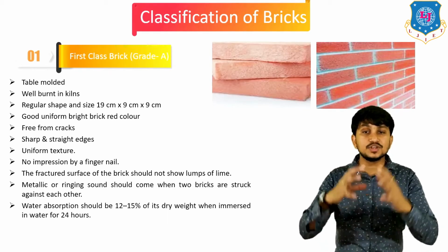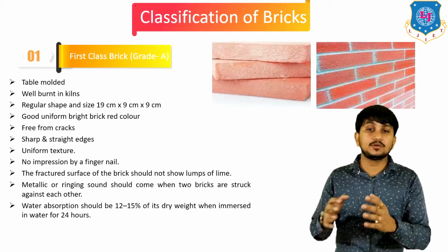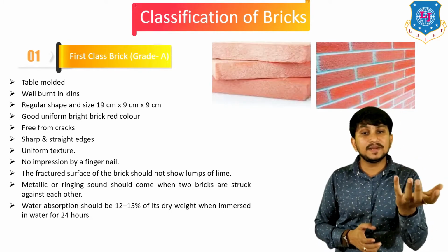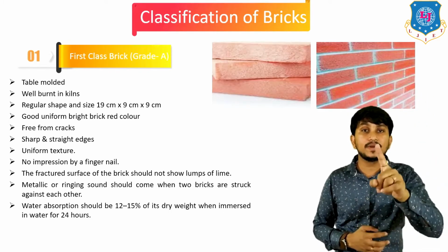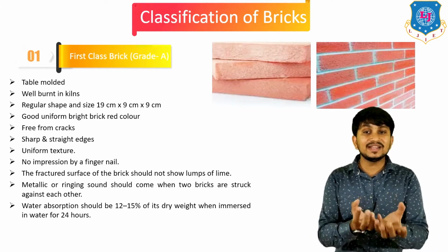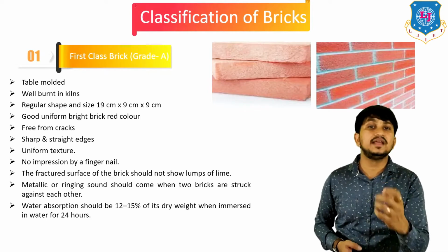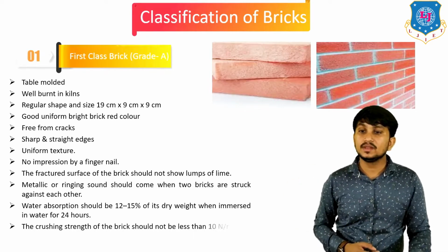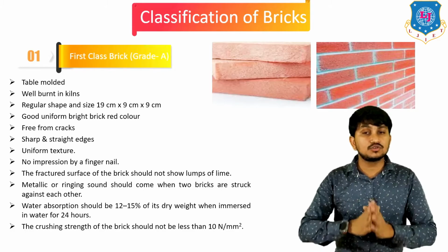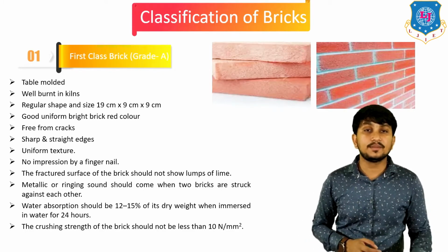Water absorption should be 12 to 15% of its dry weight when this brick is immersed in the water for 24 hours. So increment in weight is about 12 to 15%. So water absorption is very less compared to other types of brick. The crushing strength of the brick should not be less than 10 Newton per mm square.